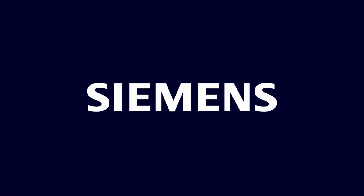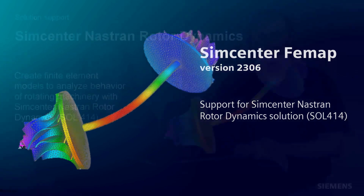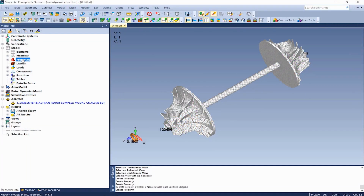Femap 2306 introduces extensive support for Simcenter Nastran's Rotor Dynamics solution sequence, Solution 414, which can be used to execute different analysis types, including maneuvers, normal modes, complex modes, harmonic response, and transient analysis of rotating structures.